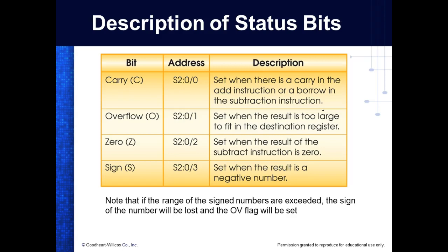But what's it going to do? It's going to give you an indication. Inside the status file, we have a carry, which means we carry out of that, right? Overflow means we change the sign. This flag indicates the results of the math operation for 0, which is what we just did. So if I add a positive 5 and a negative 5, it gives me 0. If I look at that flag bit right there and it came up 0, it would tell me that the two numbers were exact opposites, right?